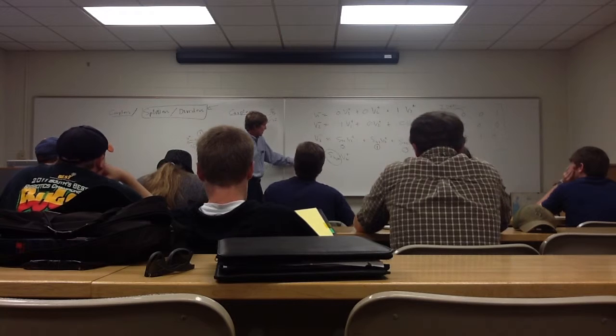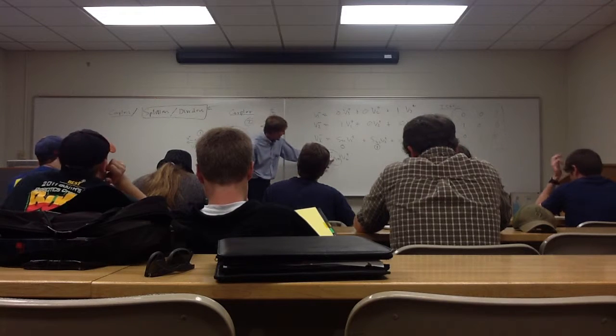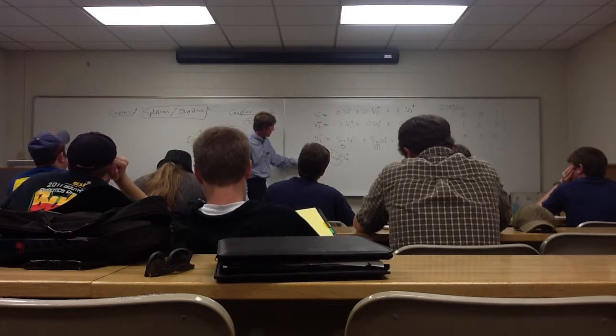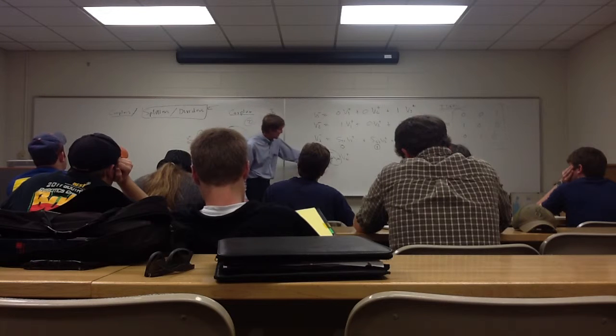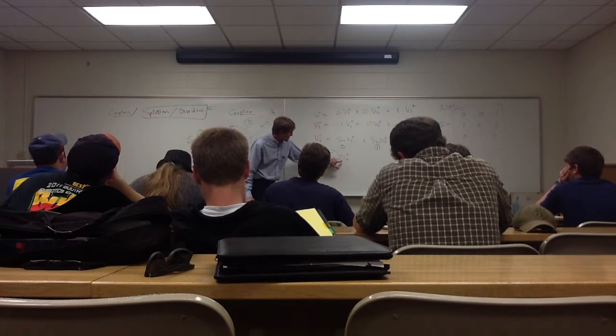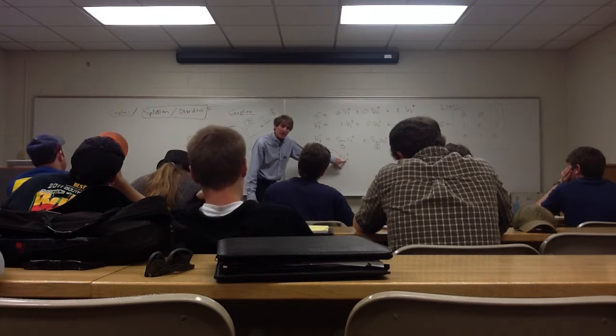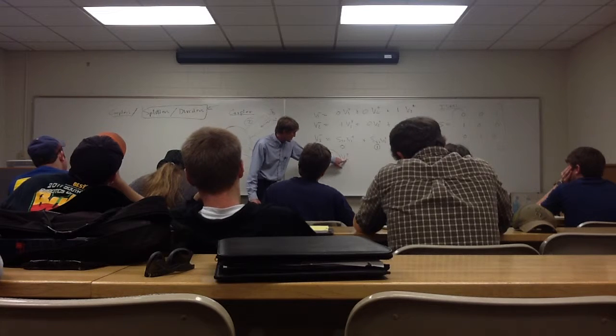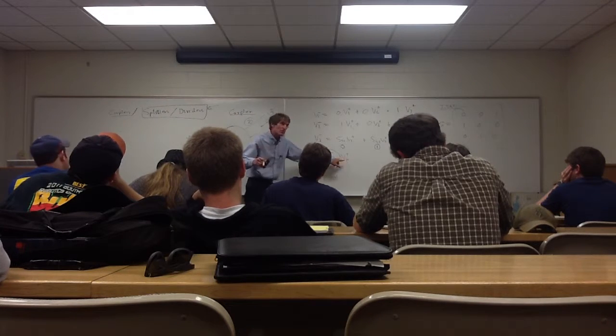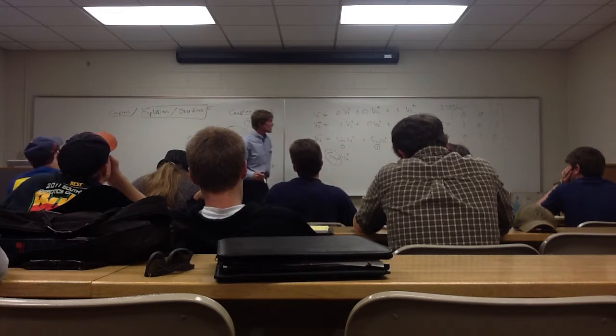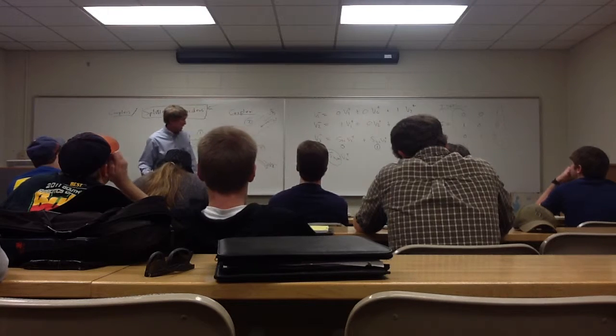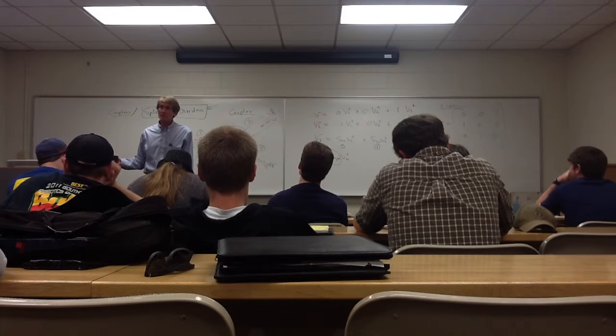Whatever I want coming out, the S parameter has to do with this number, say it's 2, and the coupled signal from the incoming port, say it's 3: 2, 3. If this was the third port, the input to the third port coming out of the second port, then S23 would be 1. Does everybody see this, class?